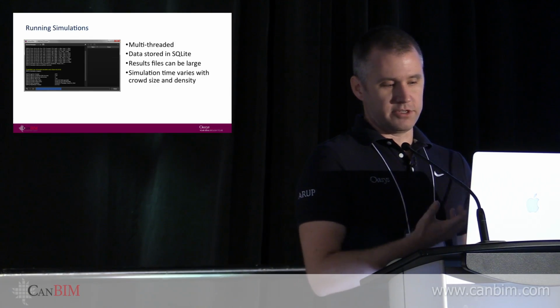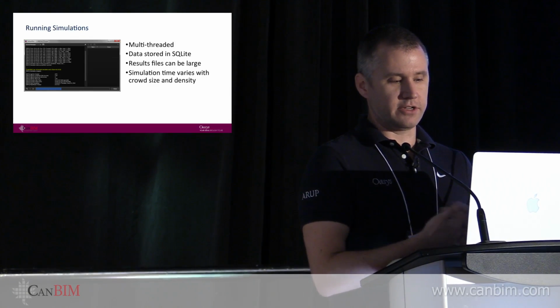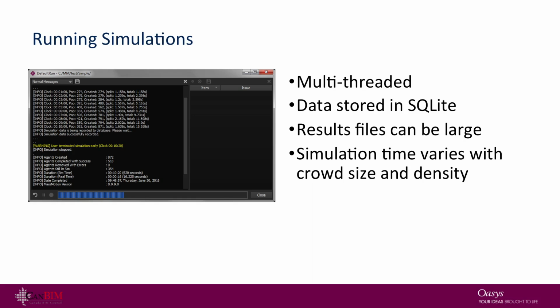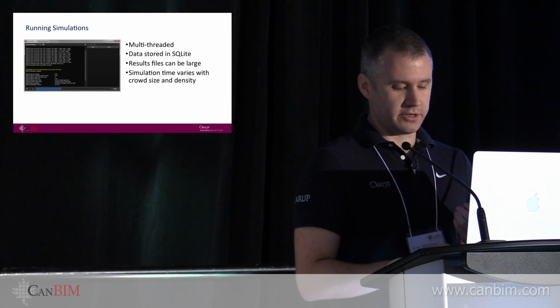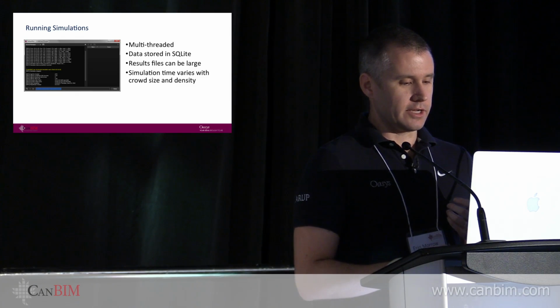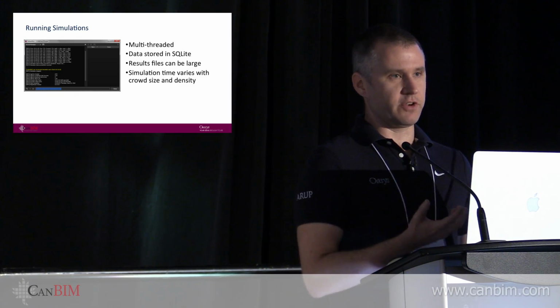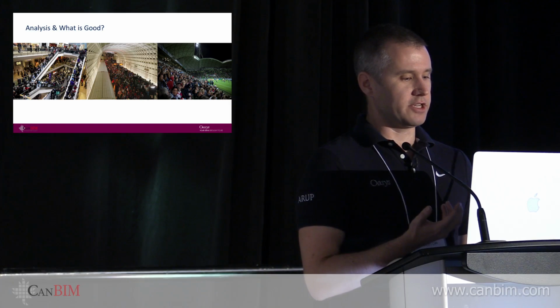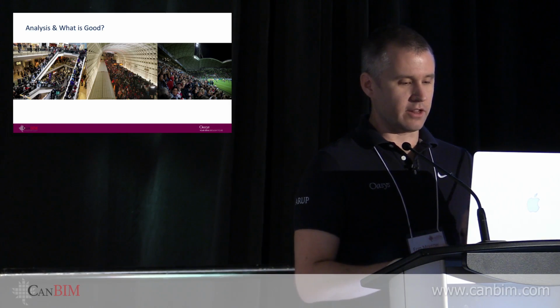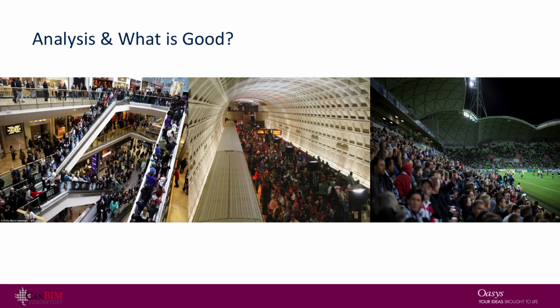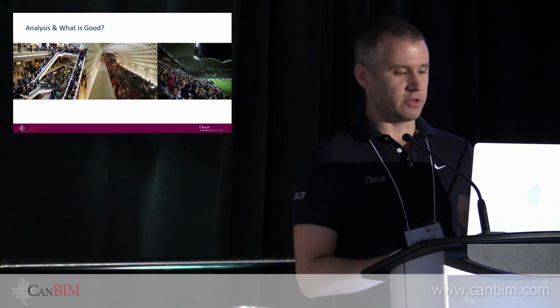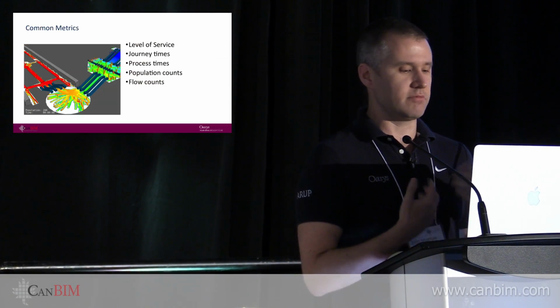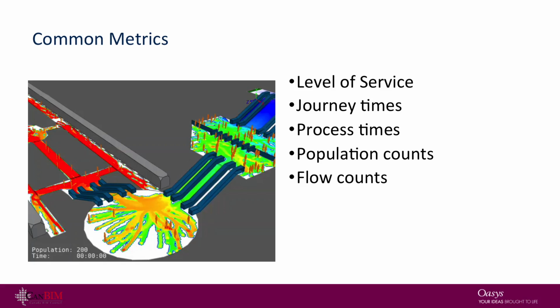And then finally, there is the running of the simulation and storing data. These simulations can produce quite large amounts of information, but the intent is that once you've got this set of data from the simulation, you can then go in and analyze what the results are, what the performance of that building is going to be in terms of density, journey times, that sort of thing.